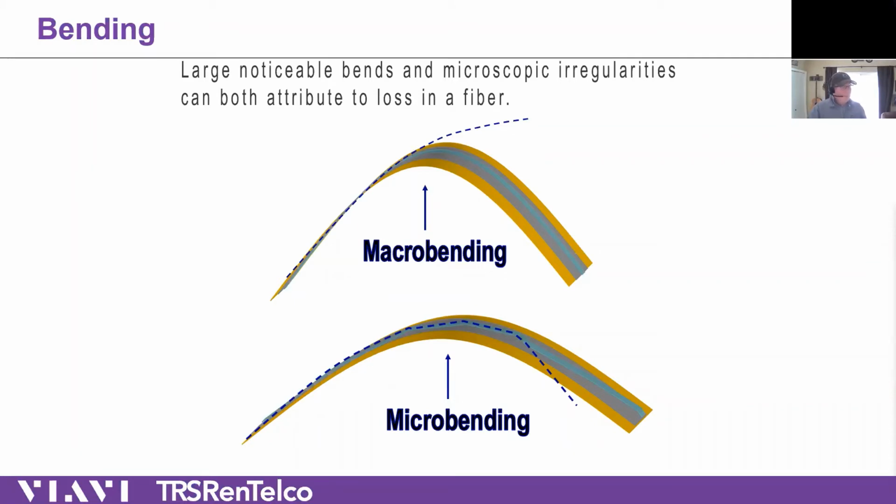Or the inverse, not enough fiber. So what do you do? Pull a little bit, you try to stretch it. And glass bends, but it doesn't stretch. So then you pull it and you make a right angle right at the connector. Right? So you take something like this and you go, boop, and you put a nice tight bend right there. We see that a lot in cabinets where they plug them into the device here and then they just let them fall. And that becomes a massive problem. That's a macro bend, and it causes a massive problem.